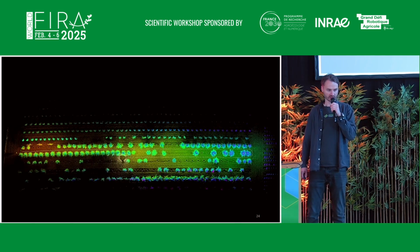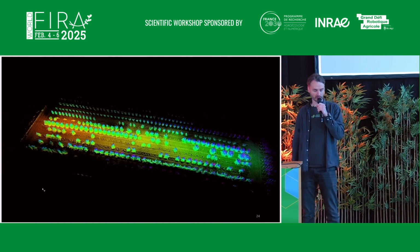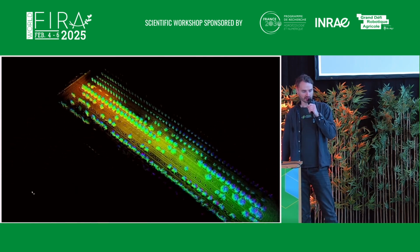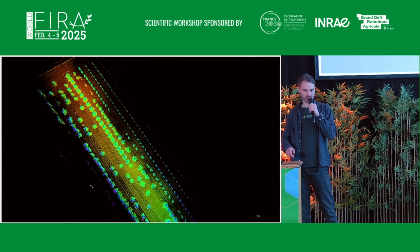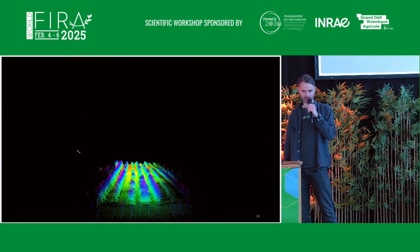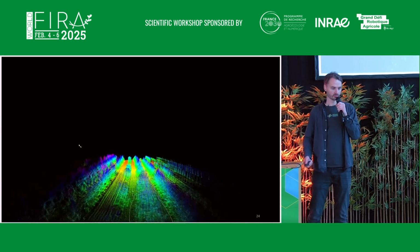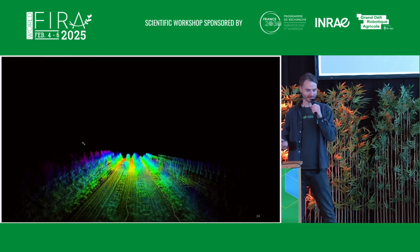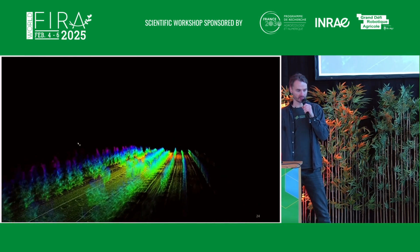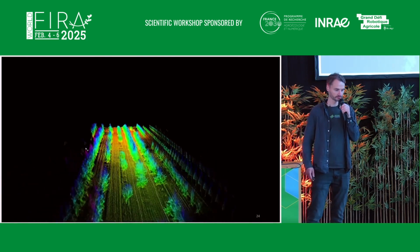Here a machine is driving autonomously through an orchard, or actually a tree nursery, and the system is localizing only using 3D LiDARs. The nice benefit is that we get a 3D map out of it, where we can do tree analysis, for example, but also use this map to derive the rows for mission planning at a later stage.